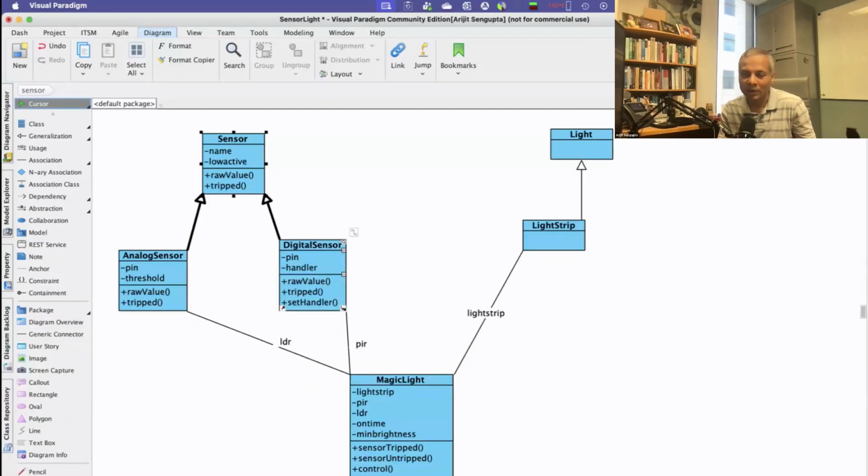We obviously don't want to get a spike that then goes away. Those controls are direct: you have to use a screwdriver and change the potentiometer. But at the end of the day, it gives you one output that is high when motion is detected and low when motion is not detected. That's it. So, one of two values.